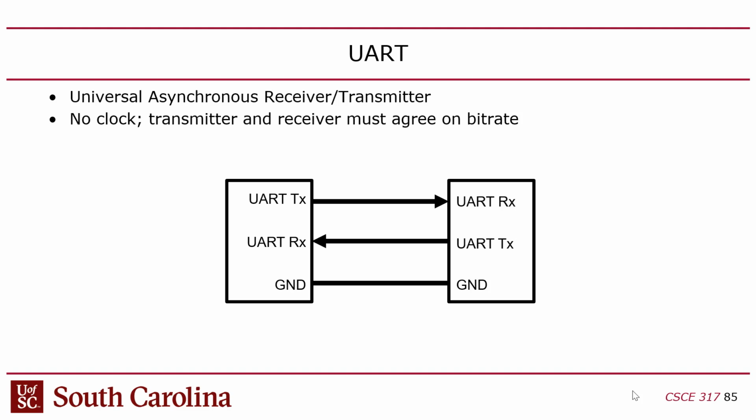You plug your serial cable into your switch or your power distribution unit or whatever it is you're trying to talk to, your oscilloscope. A lot of things have these UART connectors on them, or your FPGA, and it just doesn't work. Usually, in my experience, it comes down to trial and error to figure out. I mean, you could read the documentation, but who does that, right? So usually I end up trying all the different speeds till I find one that actually works.